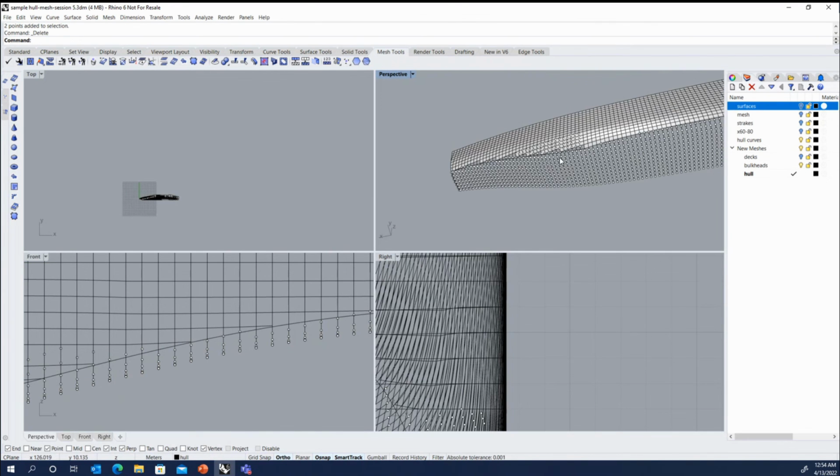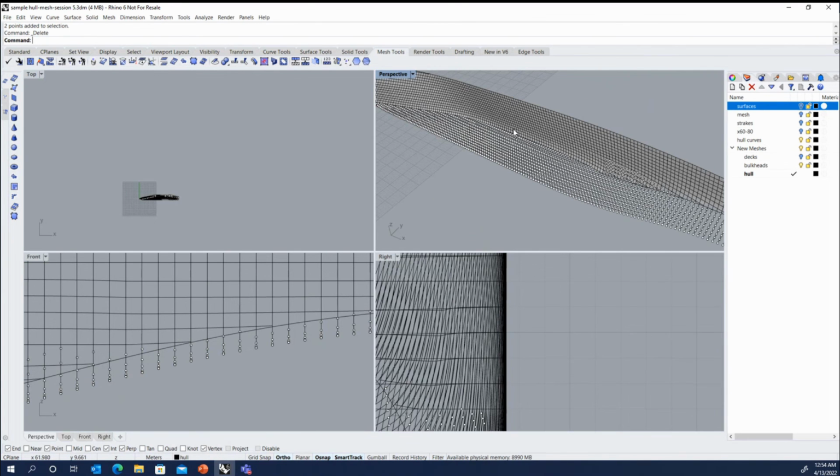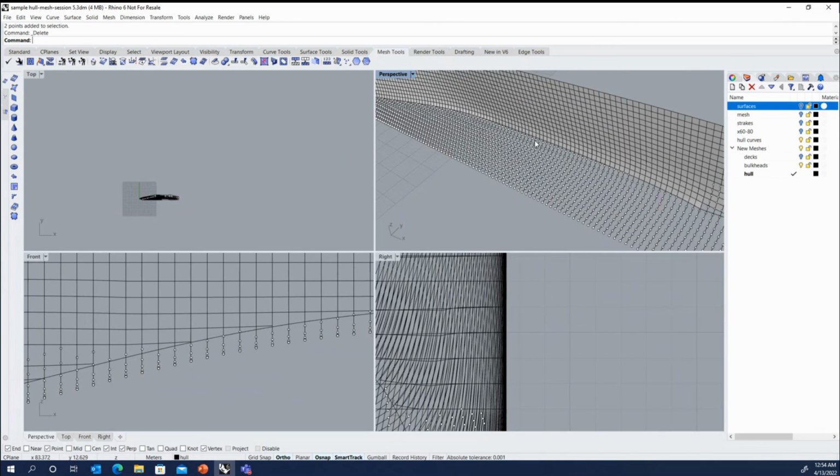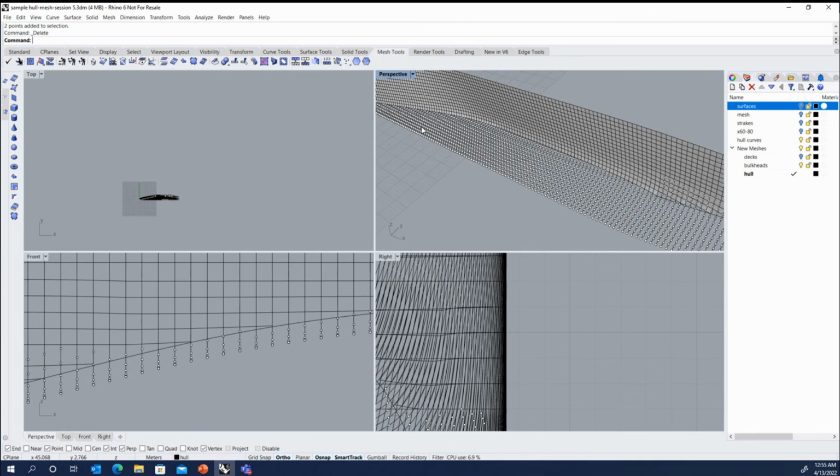You get an idea for how we would finish this up. You get a good idea of how exactly these meshes would be made, because now all we have to do is select these points, extract the bottom points on the existing shell mesh to make sure we get a good connection there, and we can create that bottom mesh.